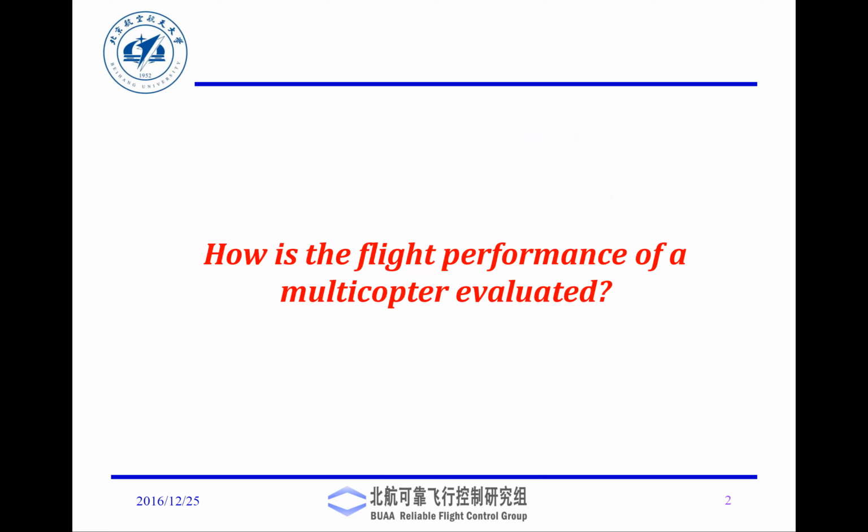So the most important thing is we want our quadcopter or multi-rotor to fly. And there are 2-3 things when we say flying. First, we want it to hover stably. What do I mean by stable hover? Stable hover means the thrust generated from each of these props should cancel out the total weight.